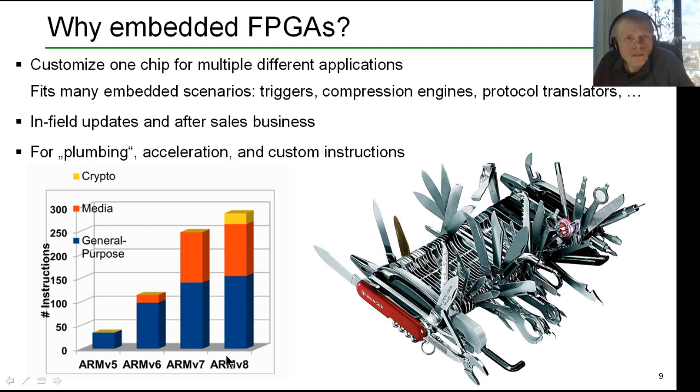If you really think about it, the more instructions you add to a CPU, the more you underutilize your CPU, because at one point in time you can only fire one instruction or a few instructions. So this gets very expensive, and you have to keep in mind that on a RISC CPU, because nothing is really micro-coded, each extra instruction costs you real estate in terms of area, may slow down things, and so forth.